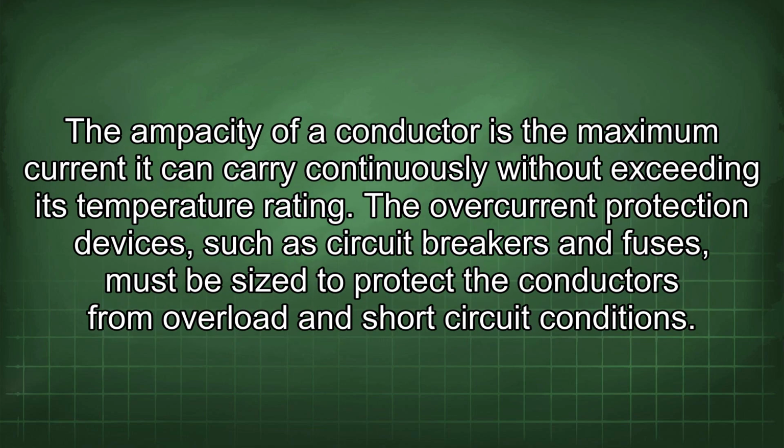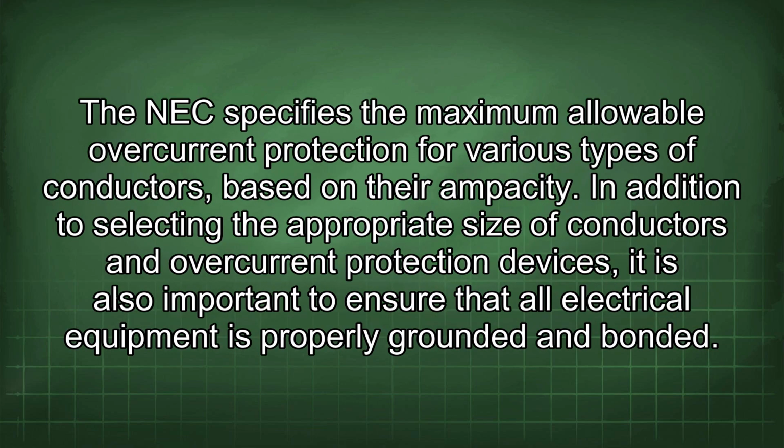The ampacity of a conductor is the maximum current it can carry continuously without exceeding its temperature rating. The overcurrent protection devices, such as circuit breakers and fuses, must be sized to protect the conductors from overload and short-circuit conditions. The NEC specifies the maximum allowable overcurrent protection for various types of conductors based on their ampacity. In addition to selecting the appropriate size of conductors and overcurrent protection devices, it is also important to ensure that all electrical equipment is properly grounded and bonded.